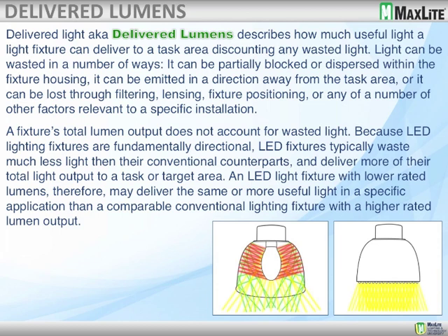Dan's asking, isn't foot candles a bit misleading when you're comparing HPS to LED? Dan, I would beg to differ and say to the contrary, it is really the only way to measure accurately. We can look at cut sheets that talk about lumen outputs, but that doesn't tell us how many foot candles we're going to have in our given application. When you do a lighting layout, one with the LED technology, one with the, let's say, incumbent technology, it's 100%. Those foot candles are exactly what you're going to have, and I would say that it is the best way to compare. Otherwise, you don't really know what you're getting without a layout.